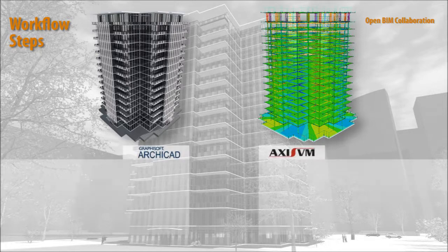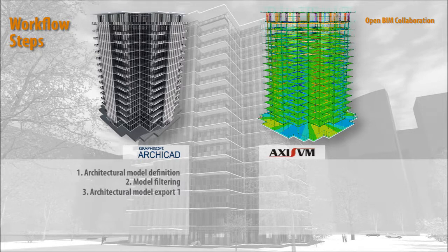Let's start with the architectural model. Architects create an initial model version based upon the client's request and the given building site. Architects filter the structural elements by using element classifications, layers, layer combinations, display settings, selection modes, and so on, to prepare the model for export. Of course, the entire project without any filtering could also be exported. The architectural model is exported in IFC format.